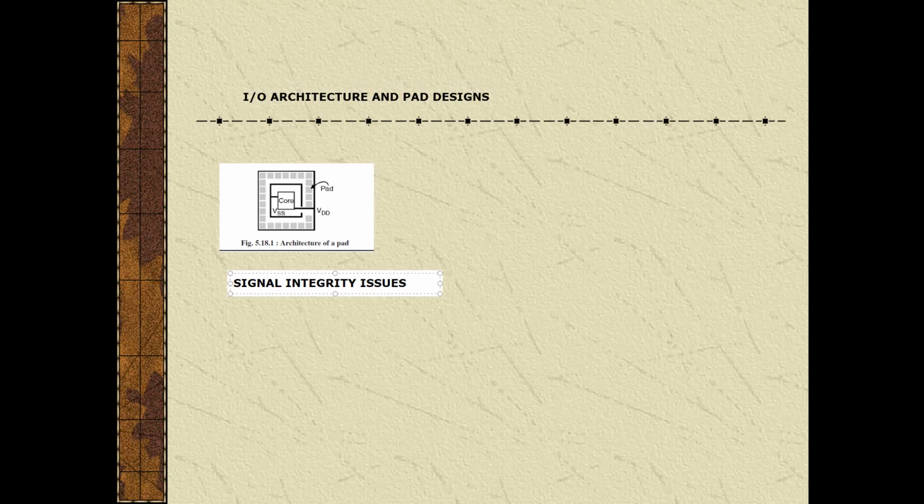In recent days, signal integrity is a critical issue for VLSI designers. The signal integrity problems are related to electromagnetics, in terms of EMI and EMC. In digital system applications, the signal is transmitted from one component to another in the form of logic high or low. At the input of the receiver, a voltage above the reference value is taken as logic high, whereas a voltage below the reference value is taken as logic low.